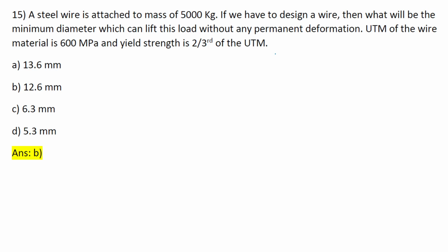Did you get the answer? Yes. How did you do it? See, sigma y is equal to 400 MPa. Which formula did you use for sigma? 5000 into 9.8 divided by pi d squared by 4.